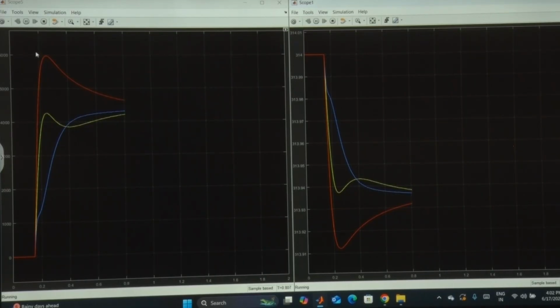Now you see, this one is quite high compared to the other two. So initially, as I told, the source which is electrically closer to the load will give more power. So this is giving more power, but what this is doing is limiting the other sources from giving power. The problem this may create is that it may lead to instantaneous overloading. So it is very essential that we bring them to the same power. How are we bringing them to the same power? By changing the frequency.